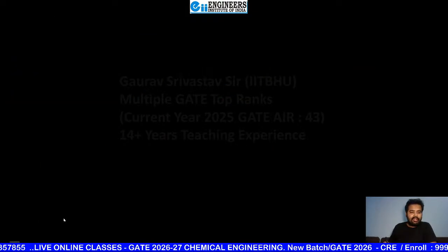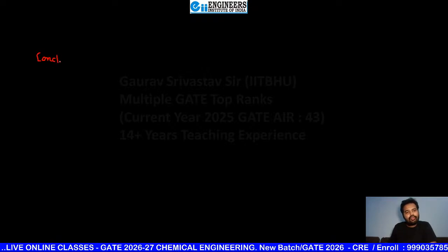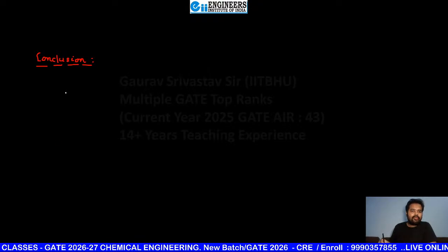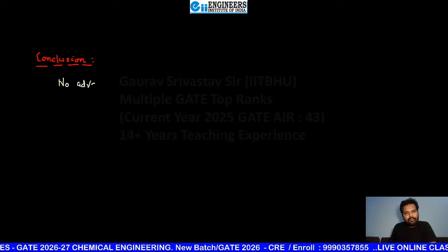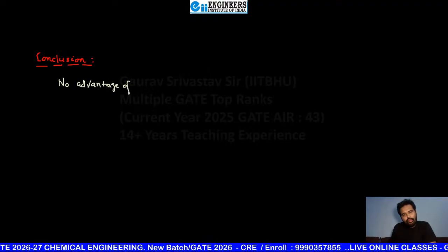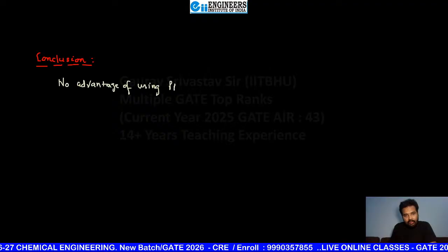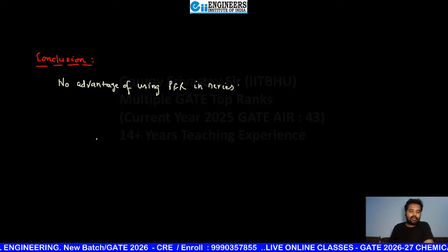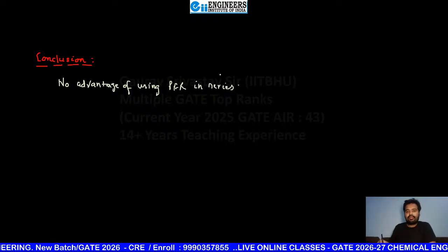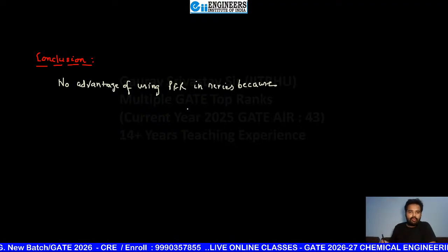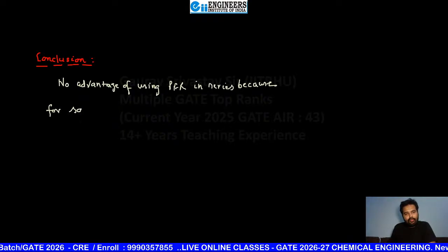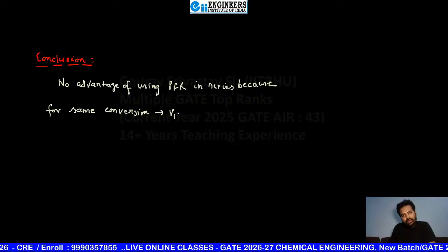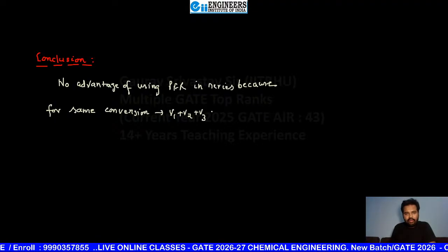Okay, so what conclusion can we give here, my dear students? Conclusion: there is no advantage of using PFR in series, because for the same conversion, V1 plus V2 plus V3 is equal to V.